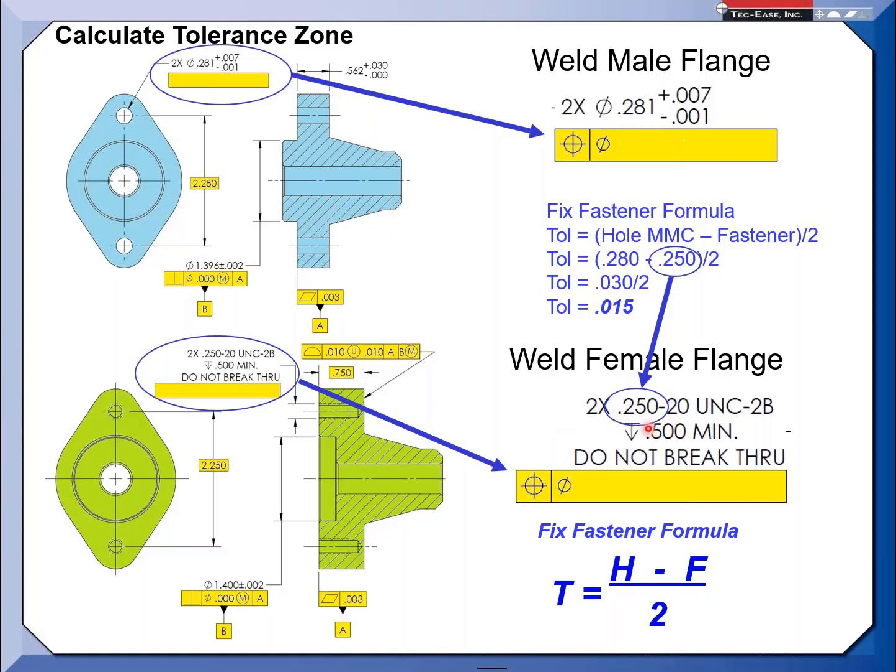Right now, utilizing this, you are going to get a little bit of cushion, because on a class 2B the max diameter is smaller than 250, but not much. The tolerances on threads don't really give you a whole lot, but there is some built-in wiggle room.